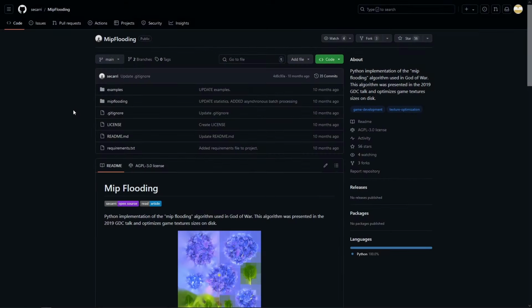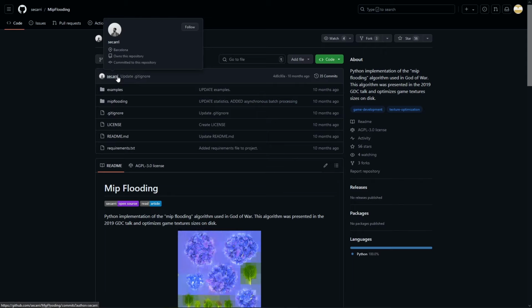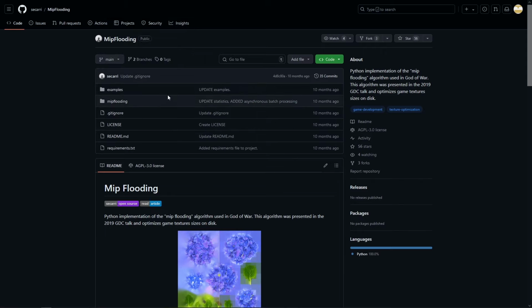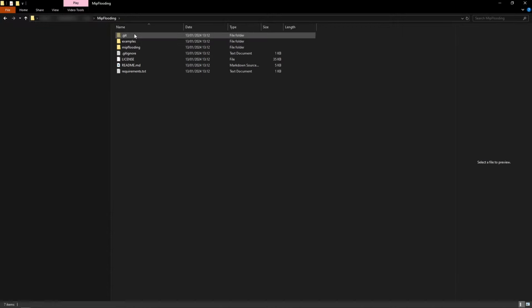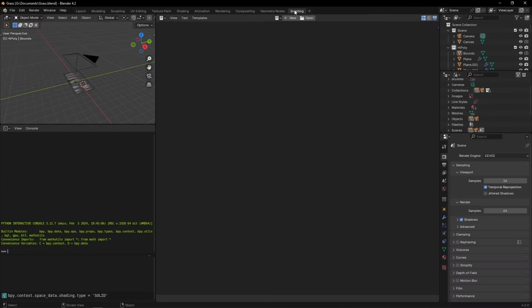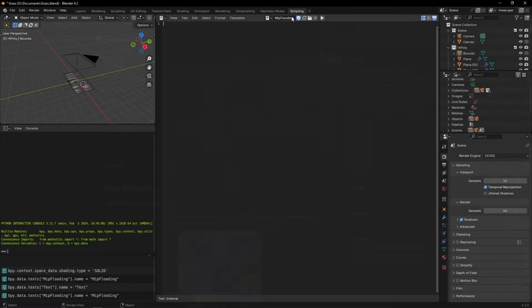Alright, so there are a couple of steps to make that Python script work in Blender, but hopefully nothing too problematic. First, I'm going to open this GitHub page. Link is in the video description below. I'm also going to give the author a shoutout. Thanks for the script. Now, if you're familiar with Git, you may get the files with a pull, but downloading the zip from the GitHub page also does the job. So I'm going to unzip it and voila. Next step is to create a Python script in Blender, like so, and use the code sample provided on the Git page.